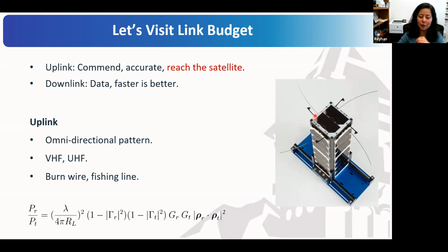For the CubeSat, we have uplink and downlink. Uplink is from the ground, where you talk to the satellite to command it. And downlink is the satellite transmitting data for us. So for the downlink antenna, no problem. We want to go with S-band or X-band, higher gigahertz, so we can do a more directed antenna pointed to the Earth.